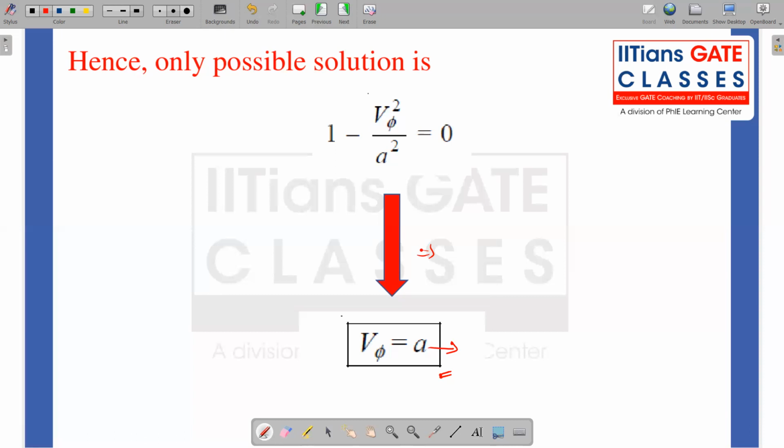So we have an infinite number of Mach waves through which the flow is actually diverging. So even from a mathematical point of view this is shown, and physics also says that through that the flow is actually accelerating. And that is an isentropic flow. If that is not an isentropic flow, then we cannot get this result.